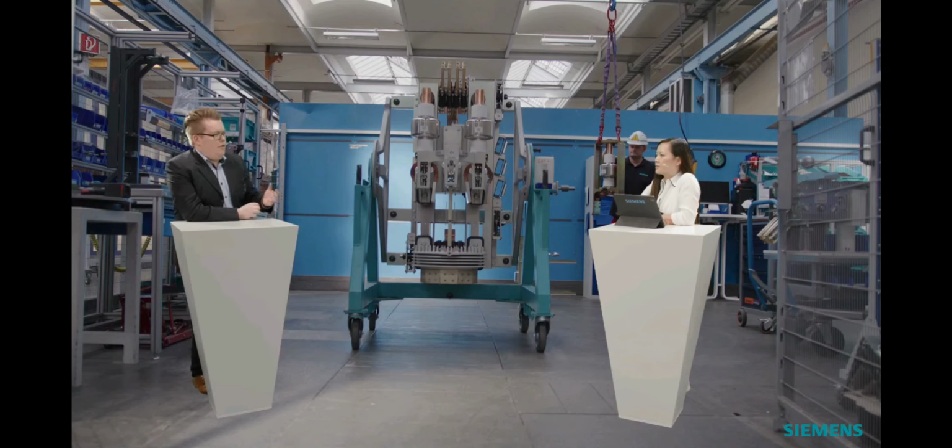Having a different or longer mechanical opening time will lead to a certain other amount of breaking current and DC percentage. But the standard does not make any difference between them. Also good to know is that there's no specific test requirement given in the standard for vacuum and for SF6. So both switching media have to fulfill the same ratings and the same test procedures. Okay, nice, interesting to hear.